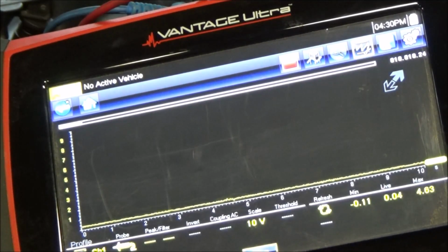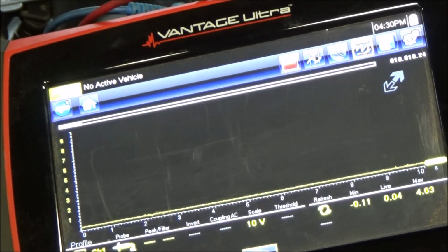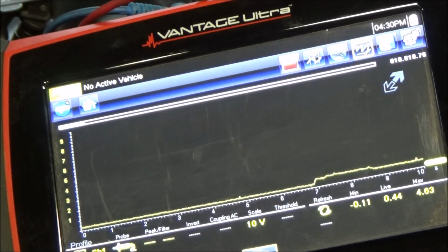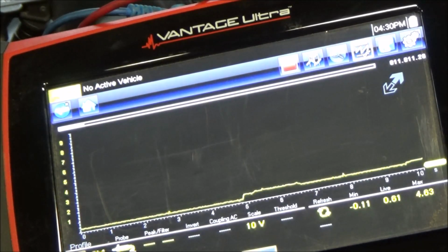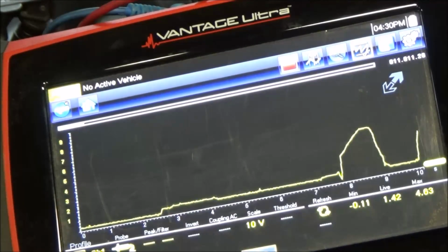Sort of, man, I'm not even sure what you would call it, but I'm just going to let off a little bit and we'll see this voltage number jump back up, as you can see there. So without a doubt, guys, this is the bad throttle position sensor. I'm just going to do it quickly now. A few quick snaps.